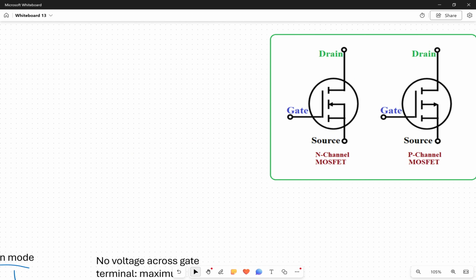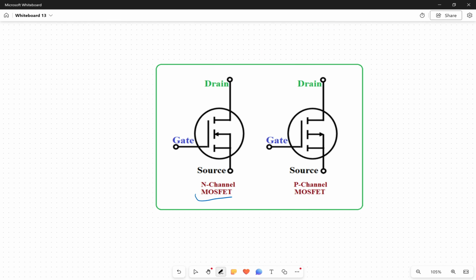In a circuit diagram, this is what it looks like. You've got an N-channel MOSFET and a P-channel MOSFET. We'll go over the differences in a bit, but that's how they look different on a circuit board. If I have a voltage applied over here for, let's say, enhancement mode, then I'll start to conduct. If the voltage doesn't meet the threshold, there'll be no conductivity over here.